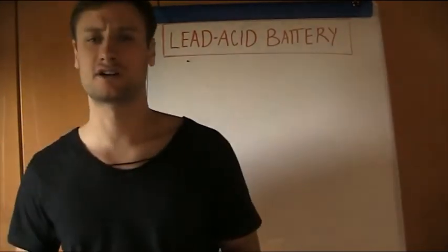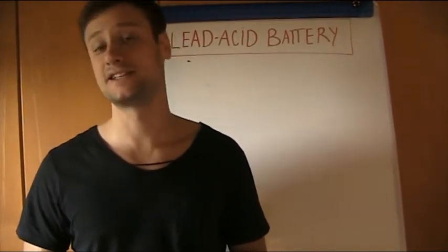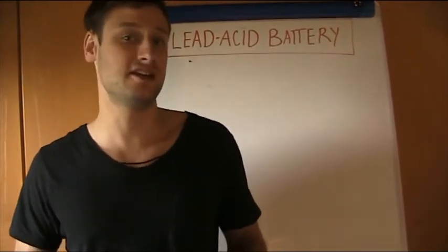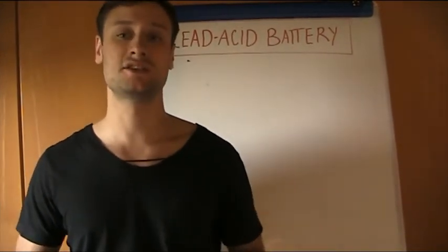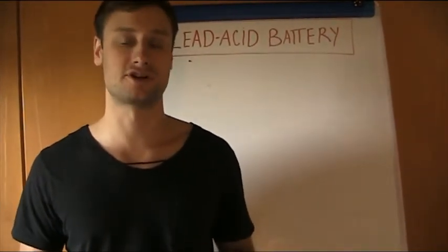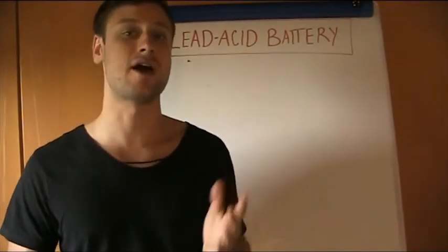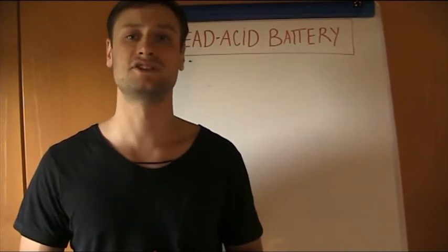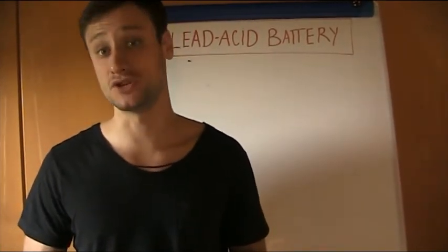Lead-acid batteries have a quite poor energy density and specific energy. What does it mean? Even if we can store a certain amount of energy, since the weight and volume are so large, the ratio of energy to weight and of energy to volume is significantly small, so the energy density and specific energy are reduced.